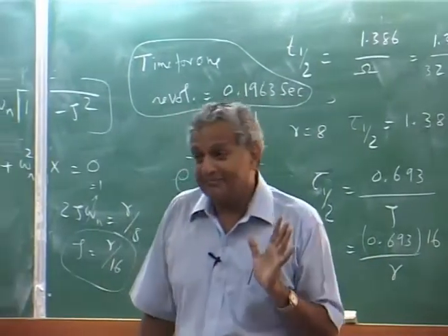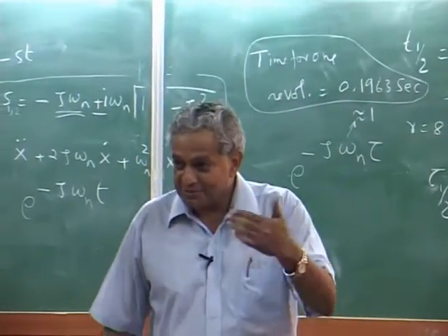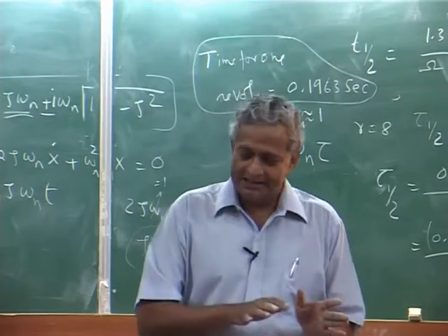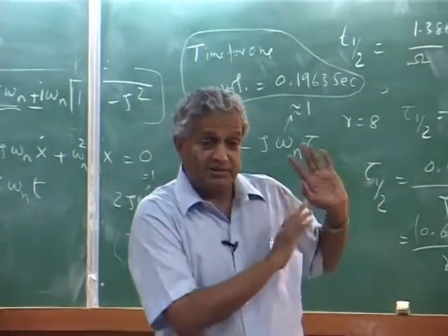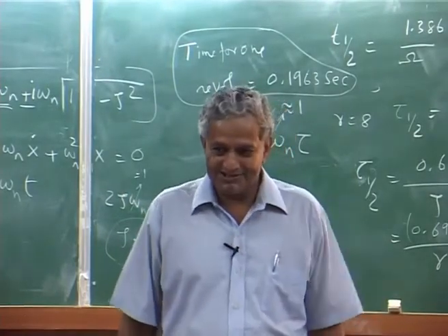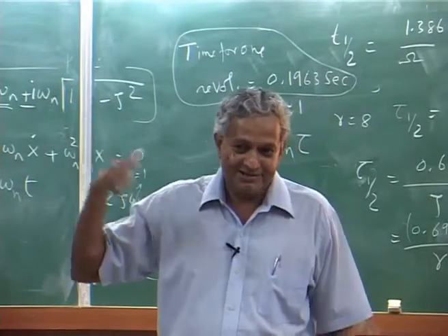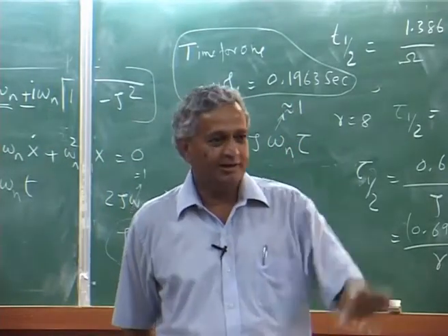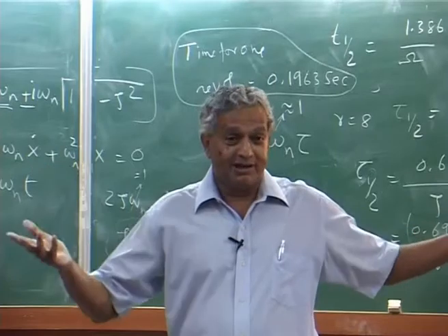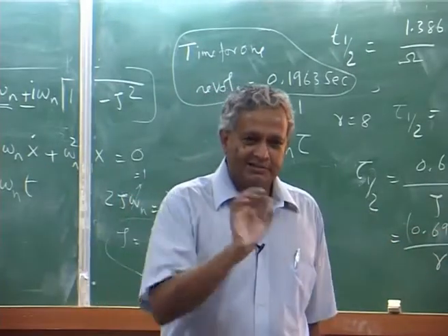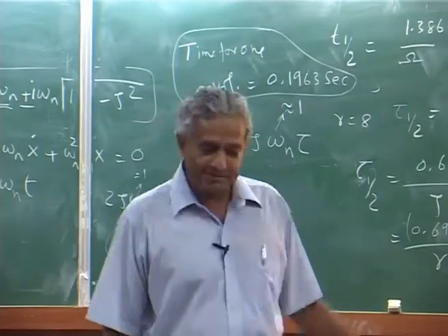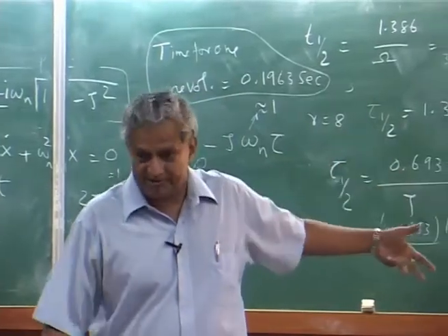This is the beauty of the flap, and this number is the one which makes further analysis simpler. You start analyzing flight dynamics based on this. When you really solve the flight dynamic equations, you will not have flap dynamics in your model, you will only have fuselage equations. And where has the blade dynamics gone? It is taken as an instantaneous change in force. That is because of this quickness.